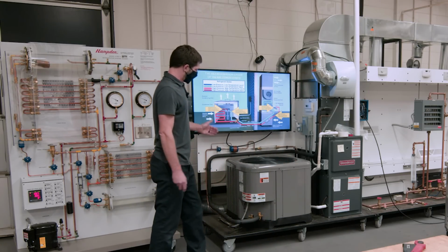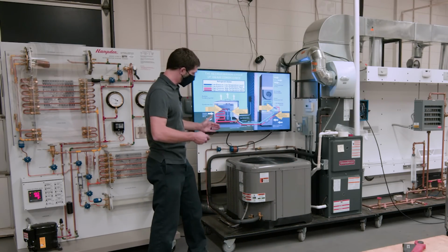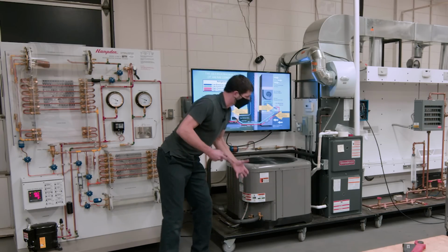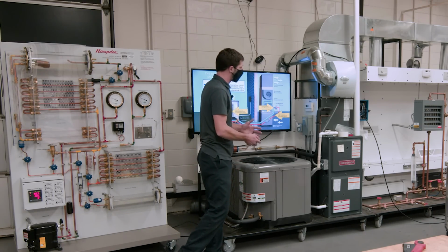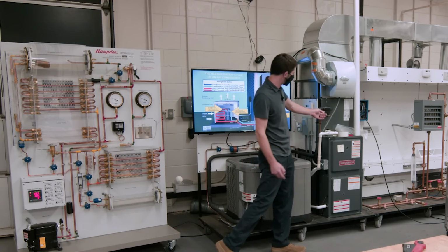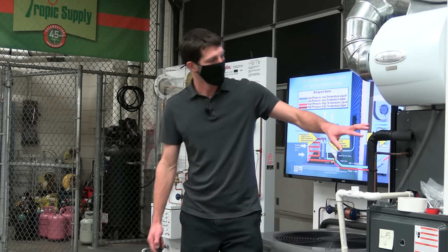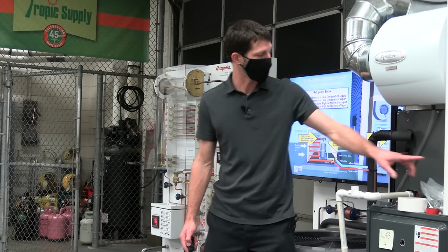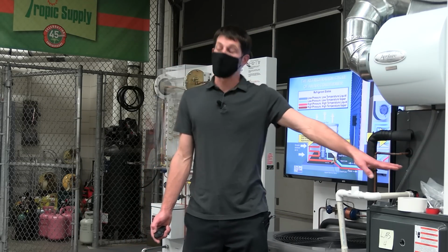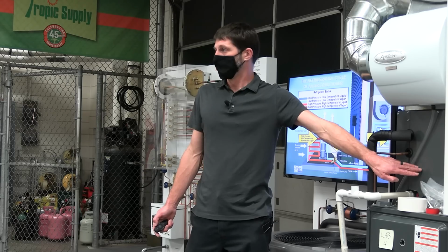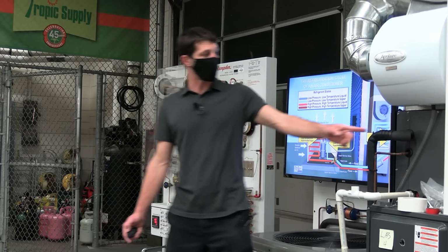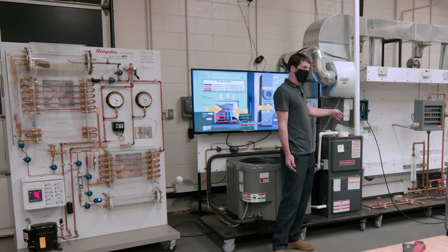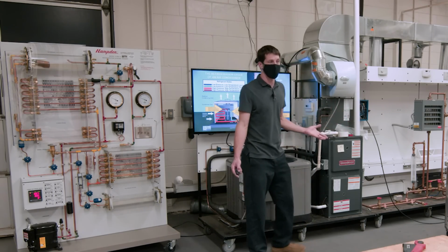And so you're going to have way too high of a subcooling, but you're also going to have way too high of a pressure. If you don't put enough refrigerant in it, you're going to be starving the thermostatic expansion valve that's on the inside here. This evaporator coil says TXV installed, so some technicians take out the TXV. So you don't want to just go by that. You want to actually look inside the evaporator coil box and see the metering device inside, because some people don't trust the thermostatic expansion valve.